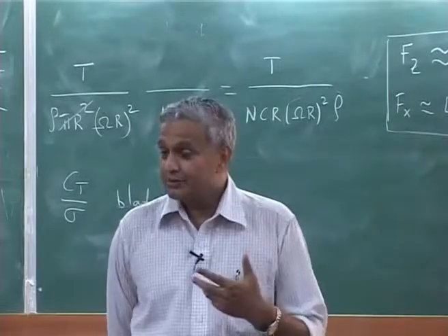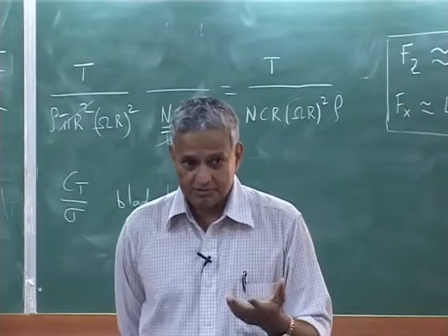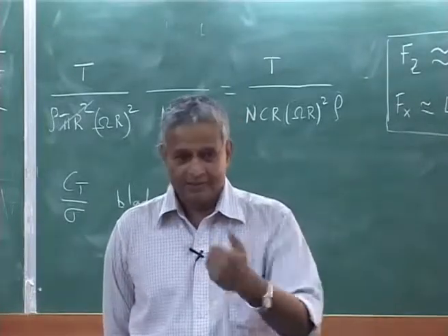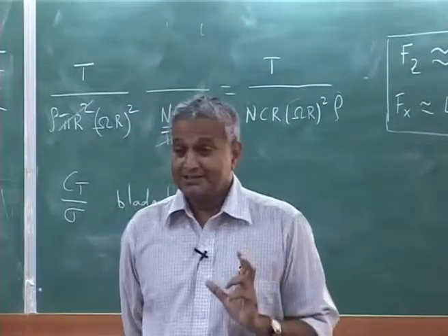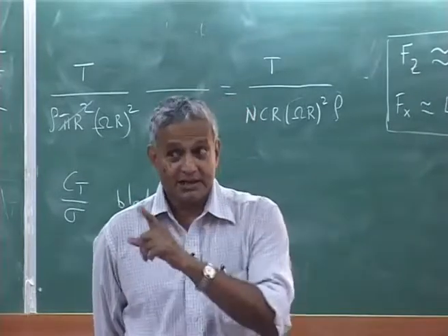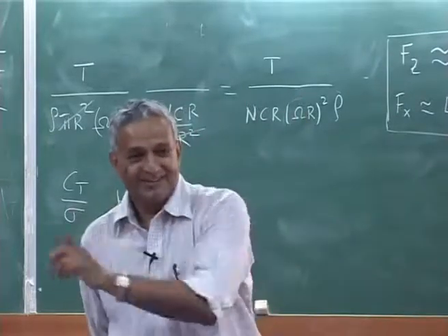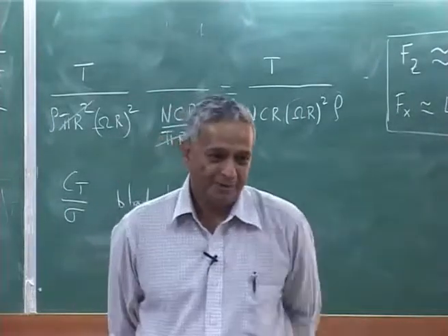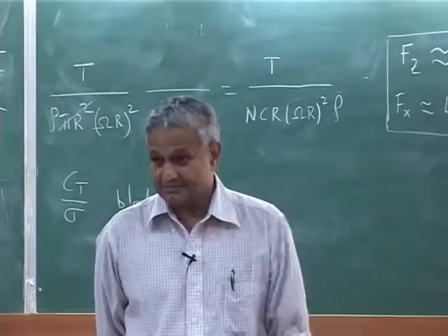Now, this is true even for forward flight, but in forward flight you also have to lift the weight, in addition to overcoming drag, etc. Now, industry requires this Ct over sigma. It is not a constant with forward speed, please understand, this varies with forward speed. This is what I gave you as a project, because this is very tricky stuff.